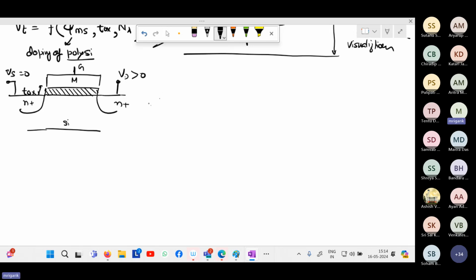But anyway, here, if you're talking about the gate voltage, you're applying a higher and higher electric field. When you're applying the gate voltage, you are creating an electric field from gate to the silicon. And if you have thinner and thinner oxide, you will have more and more electric field, or basically more and more potential drop in the silicon as compared to the oxide, right?